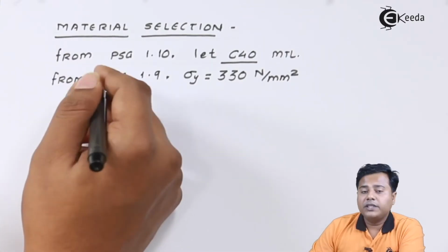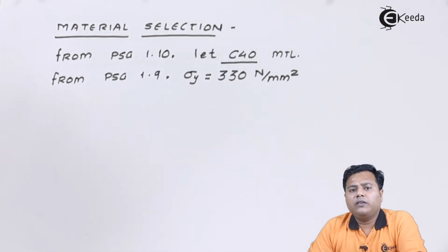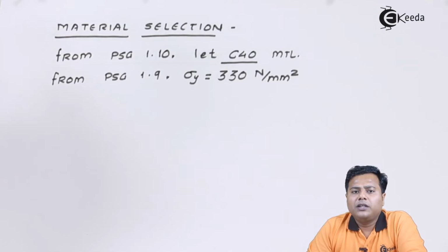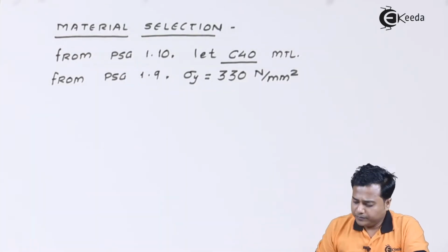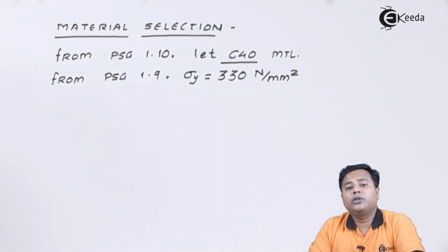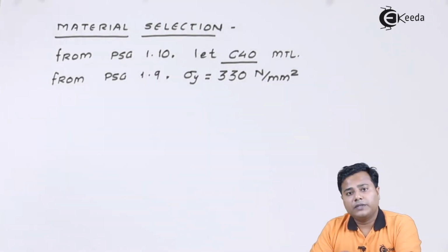Now again we have to consider some factor of safety. Now power screws actually have very heavy applications to consider. So we'll go for a better factor of safety. In this case we are going to look at factor of safety somewhere around 5 to 10. So let us begin with the initial part. If it fails, we have to come back and change the factor of safety.